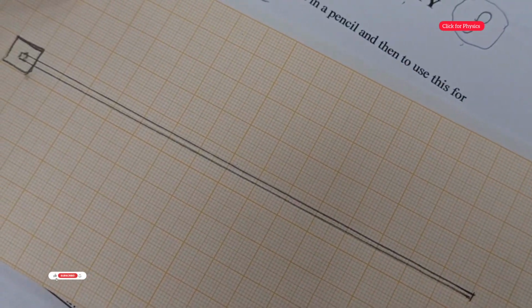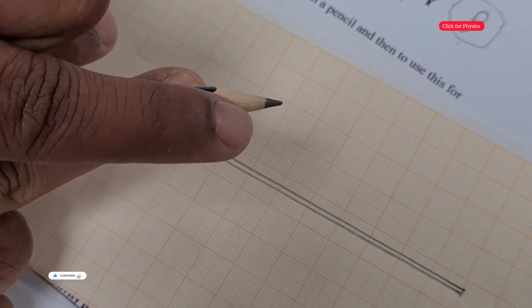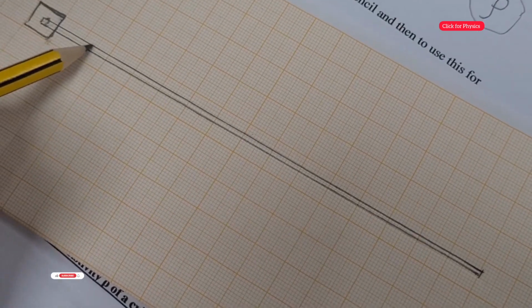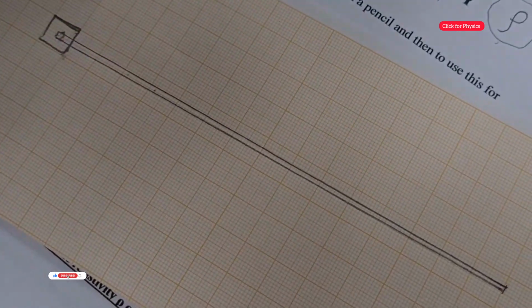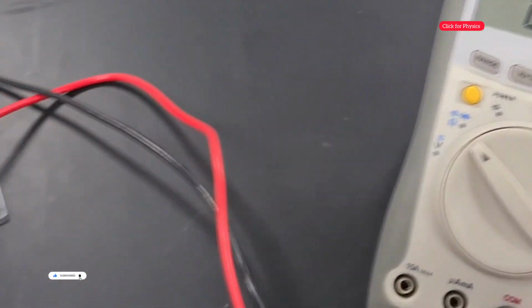After you draw this, you have to shade it perfectly using this lead, this black color, which is nothing but graphite material. You have to take your pencil and shade this box and also this pencil line perfectly. If you leave any space between these, you will not get the reading in the resistance box, because you are going to measure the resistance.